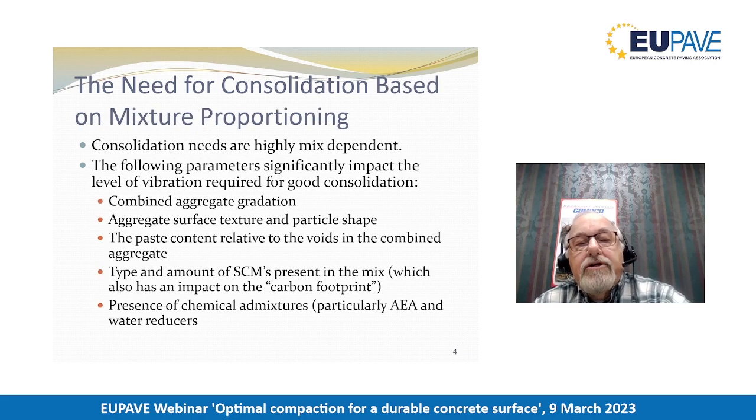So consolidation is based very strongly on mixture proportioning. Consolidation needs are highly mix dependent, and that means that for a different mix consistency, different level of workability, we have significantly different vibration energy that needs to be imparted into the pavement.